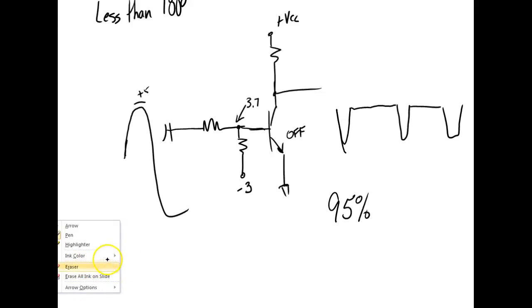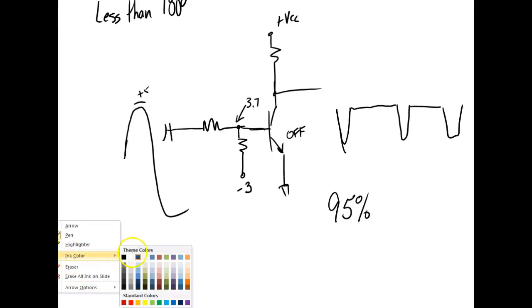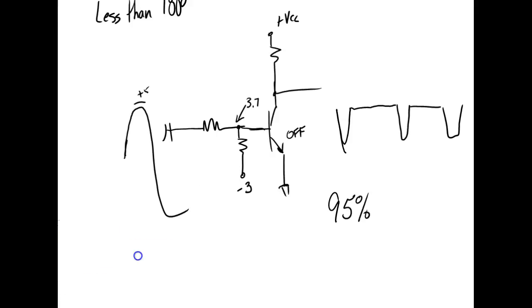And if you haven't had AC, don't worry about it. But what we do is we have these circuits that we call tank circuits that basically absorb energy and then return energy. And they consist of capacitors and inductors. So normally these guys depend on the output to be at the same frequency. And what we do is we replace this resistor right here with a tank circuit. And this circuit would be tuned to this frequency right here. So what would happen is here we would charge the tank up, and then when it dropped, this guy here cut off, it would discharge and generate the cycle.